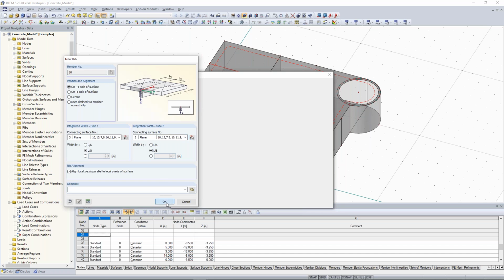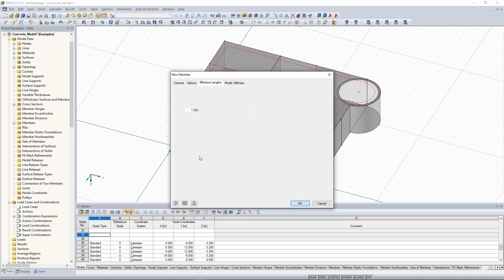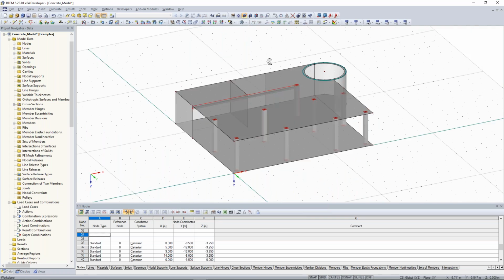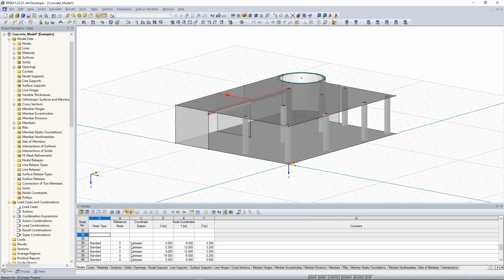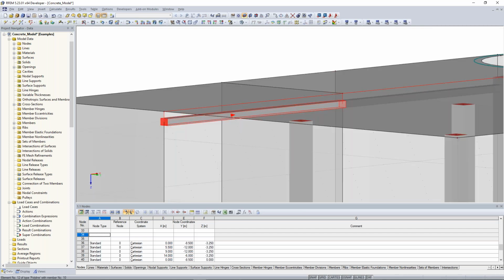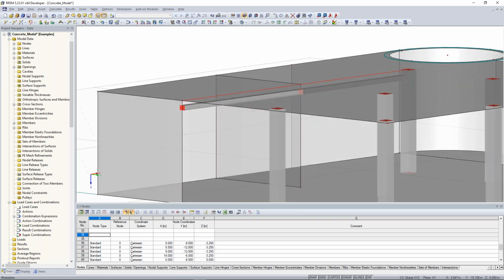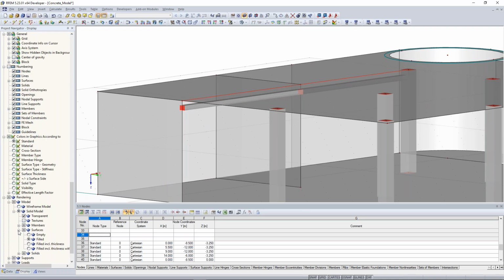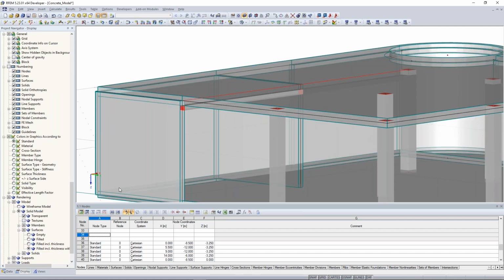I click on OK, again on OK. And now you see here this downstand beam. And you see, okay, there's an eccentricity, there's a joint. And now you don't have to do that. I just want to show you that when I go to the display navigator, go to the rendering, click here on model, solid model, surfaces, and say, okay, filled, inclusive with edges.